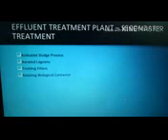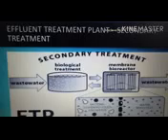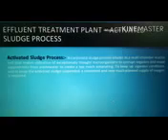In the secondary treatment process, there is the activated sludge process. An activated sludge process refers to a multi-chamber reactor unit that makes use of highly concentrated microorganisms to degrade organics and remove nutrients from wastewater to produce a high-quality effluent. To maintain aerobic conditions and keep the activated sludge suspended, a continuous and well-planned supply of oxygen is required.